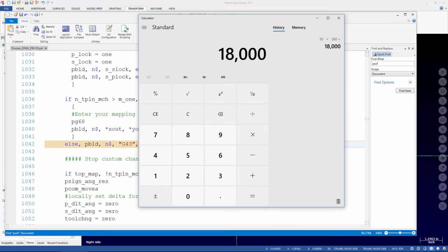I doubt this machine does. This machine probably only has a C axis address, and that's the other thing you need to test. Will it accept negative numbers? Oh, the Mori has the option, but not the Doosan. Yeah, it makes sense. So, will it accept negative numbers? Can you give it minus 20? Can you give it minus 180, minus 360? Or will it only accept values in the 0 to 360 range?